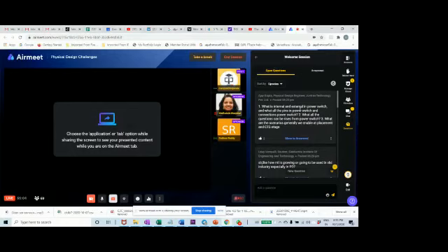Let me talk about an application. Let's say I'm using a mobile phone. I'm using the display. At that time, I'm not using the modem. Let's say I'm not taking a call while I'm using the display. I can always switch off the modem part of the design and enable the display and multimedia part. So internal switches can do that. It's a logic function that will switch different parts of the logic at different operating time frames.